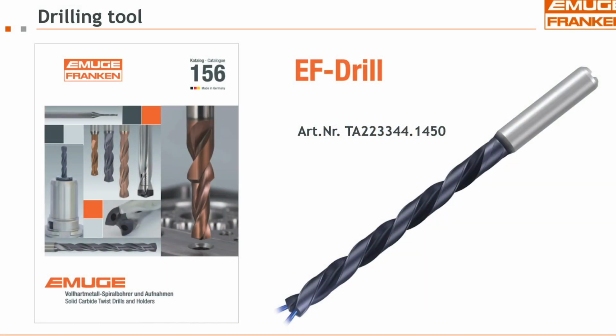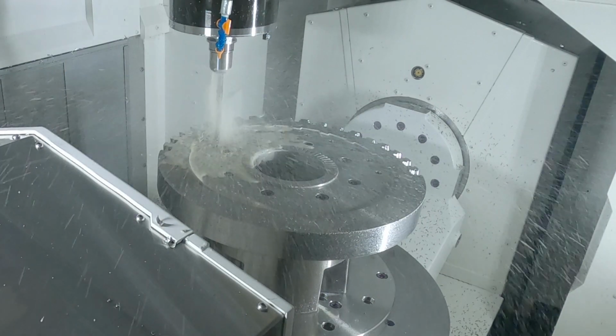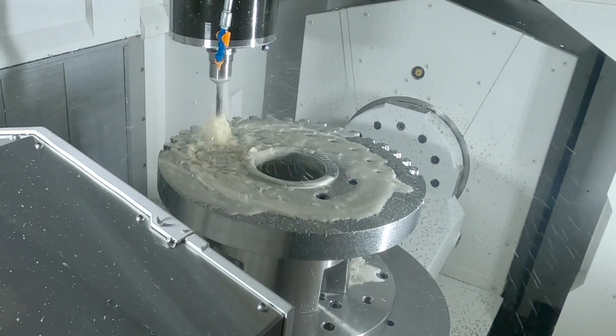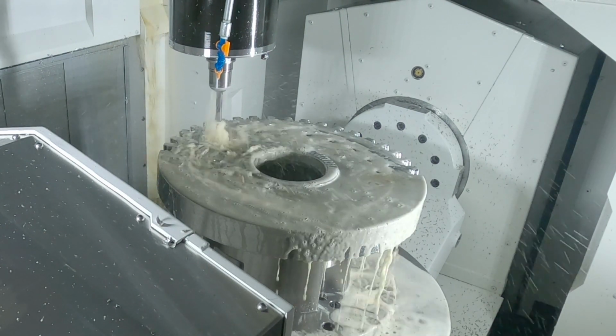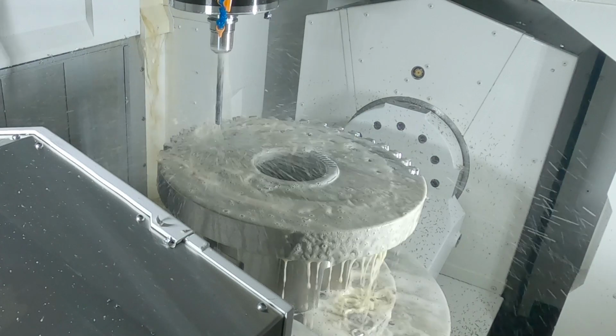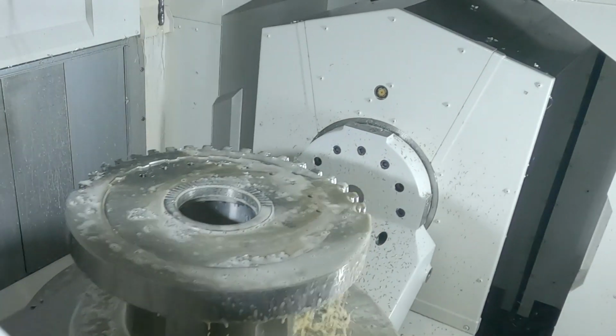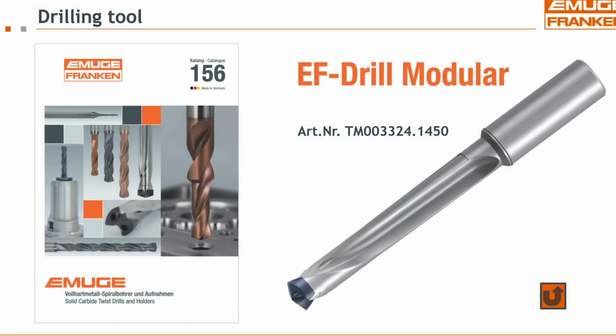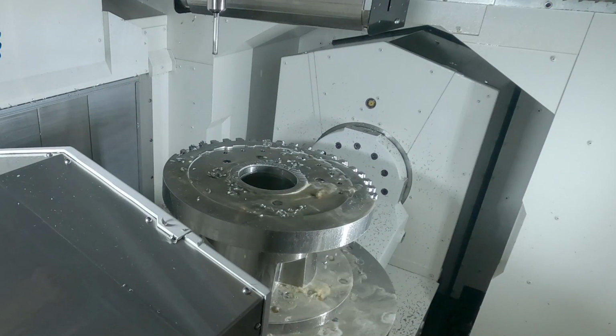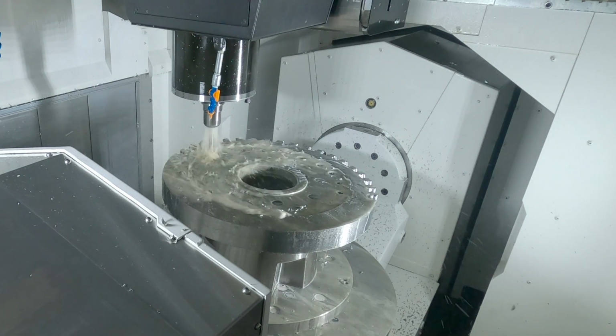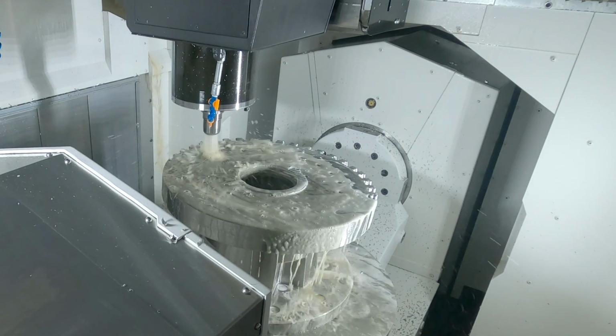Further improvements in the productivity could also be achieved with the setting of a drill operation. Even if it is with an angle, this operation can be made thanks to the position of the table, as you see, and we can drill right now with the solid carbide solution, our AF drill program. And the next tool we set now is our AF drill modular, which is actually a solid carbide head built in an HSS body.